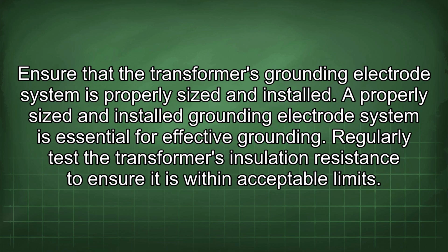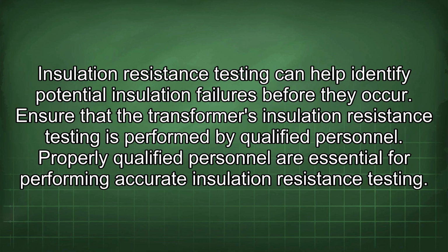Regularly test the transformer's insulation resistance to ensure it is within acceptable limits. Insulation resistance testing can help identify potential insulation failures before they occur. Ensure that the transformer's insulation resistance testing is performed by qualified personnel. Properly qualified personnel are essential for performing accurate insulation resistance testing.